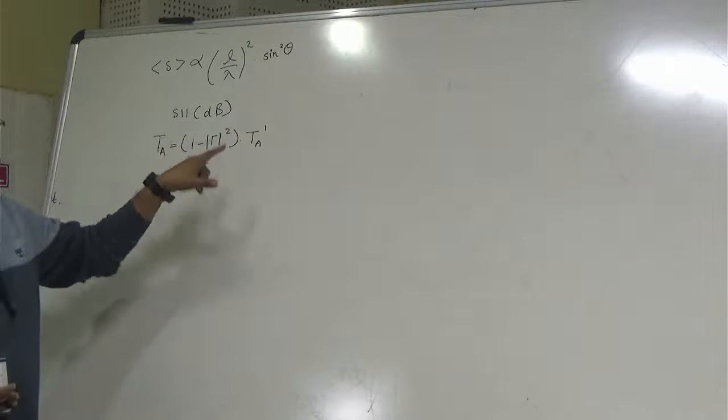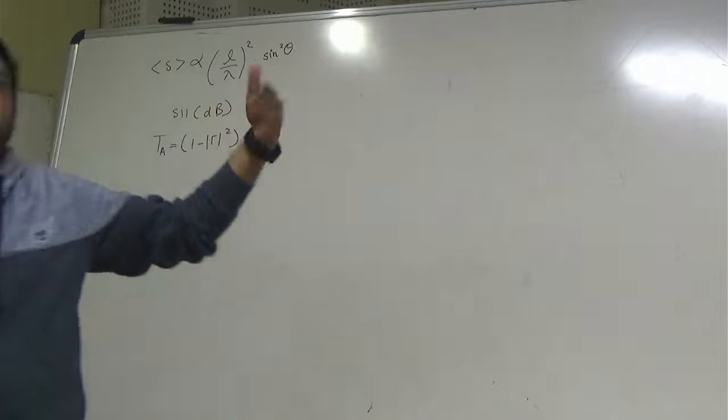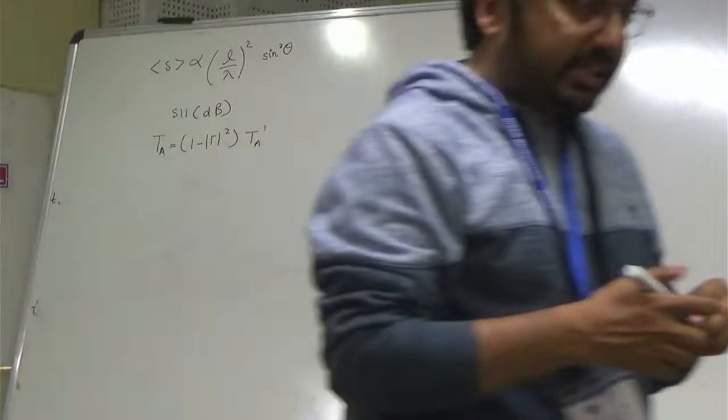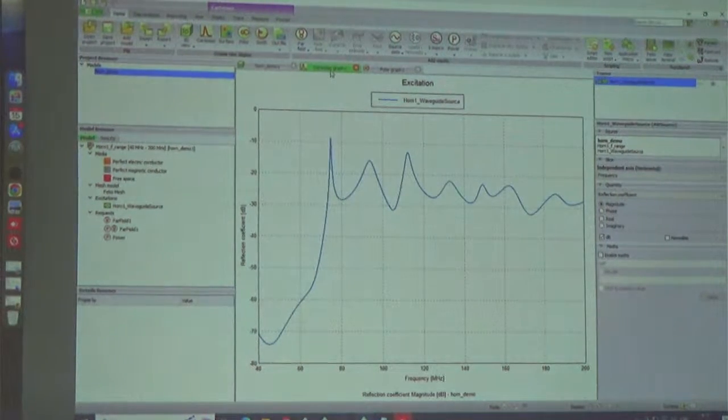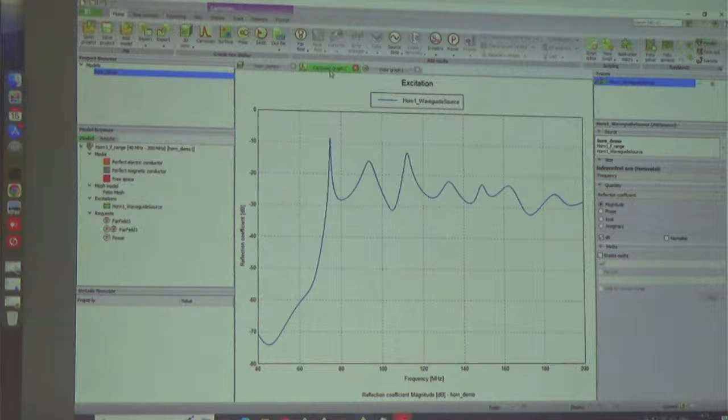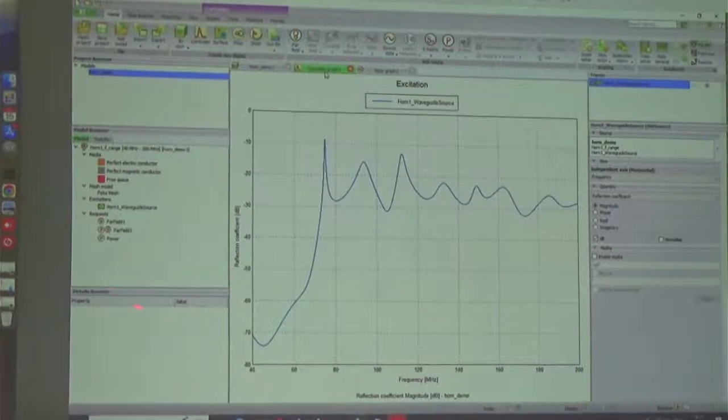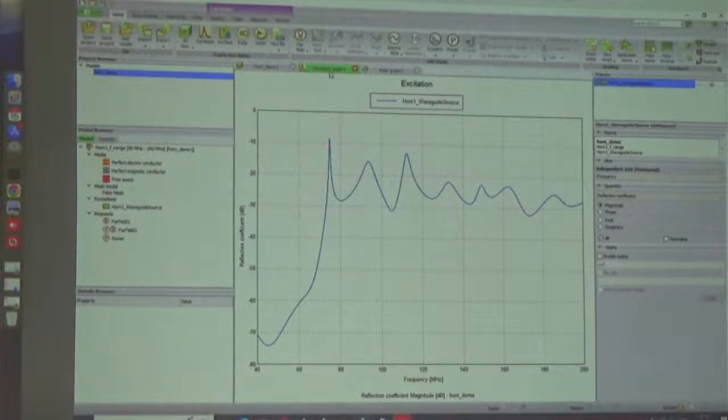This modulation term is decided by how well you are matched. We call this return loss, we call this S11, there are different terms, but they mean the same thing. And again, it's very clear: if there are any spectral features in this measurement, in this gamma, your sky signal is going to be multiplied by that, right? You can see your reflection coefficient.